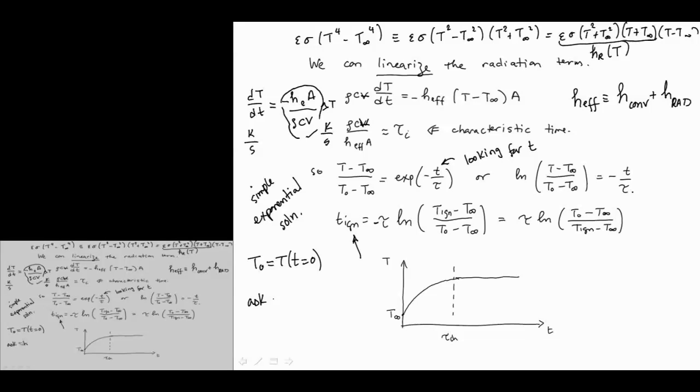what we're asking is, at what time will the sample reach an ignition temperature? We answer it by saying it's this specification. So it's tau times log of T ignition minus T infinity, taken to minus 1, so it's tau, so just invert it.